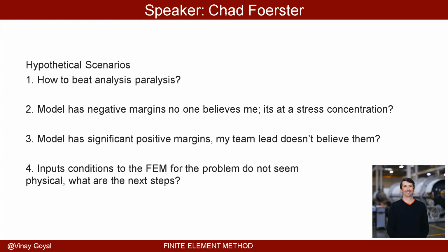And then being really, truly upfront and acknowledging the defeaturing that you have done, because there's usually some level of defeaturing. Sometimes it's extreme, sometimes it's not. That will help you explain what the situation is. Like using an RBE2: we all know RBE2s are dangerous, but they're also super useful. So just be careful.